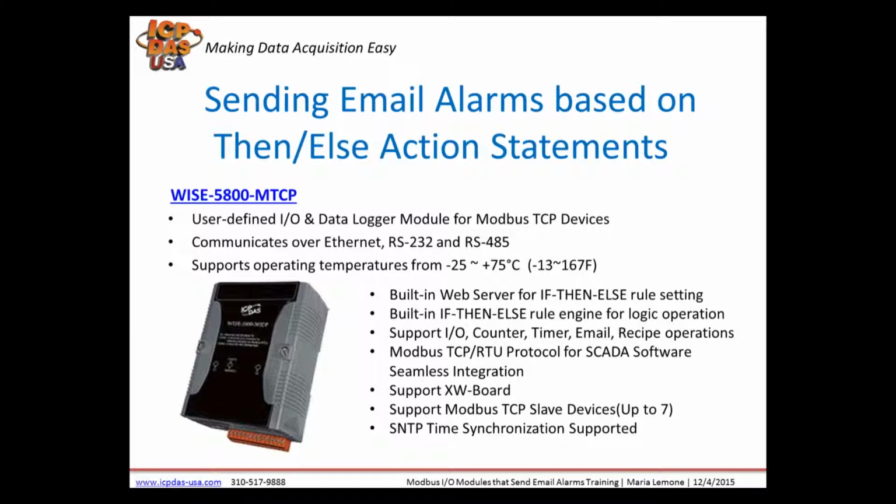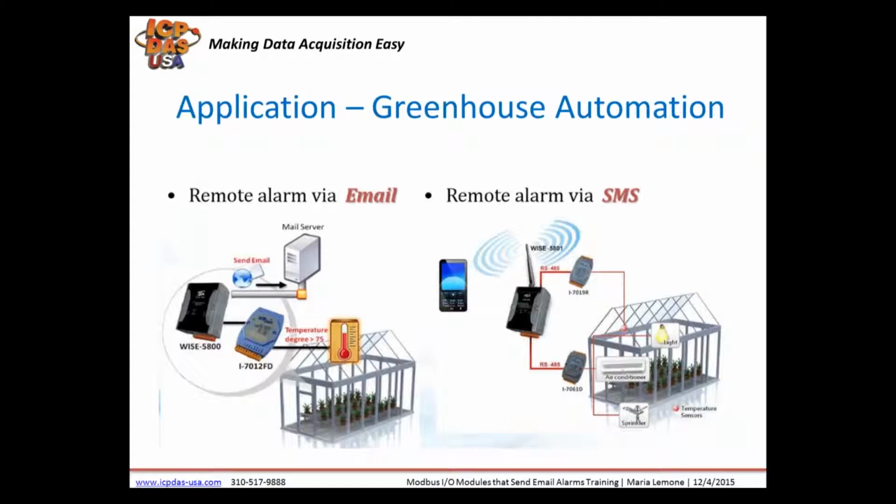Modbus TCP based data logger products like the WISE 5800 MTCP can be used to collect data from Modbus TCP devices and can send email alarms based on information. It's used through a regular web browser for configuration, I/O monitoring, and control. Remote control is easy as surfing the internet.